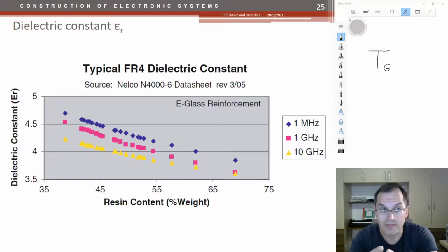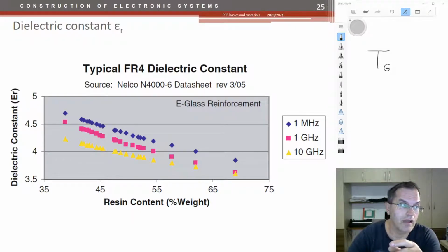And that's a problem because, I must tell you a story here. Let's say you make devices or electronics that have a high frequency antenna, let's say 2.4 gigahertz, which is quite commonly used, and this antenna is made on a PCB. If you want effective communication, you have to tune that antenna to have the resonant frequency directly at the frequency at which this communication operates, let's say exactly 2.4 gigahertz.